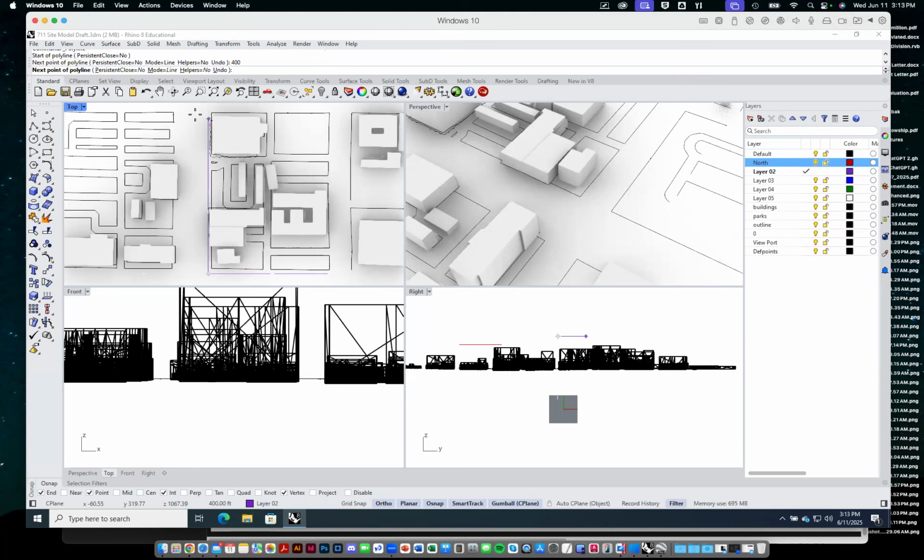So the sidewalk would never eat away into the parcel? Correct. These are the property lines for the parcels. And then we would have sidewalk. Then after this, we'd have public right of way. So sidewalks, curbs, streets, and then sidewalk and curbs on the other side. I see. So the sidewalk would eat into the 80 foot. Yes, exactly right.